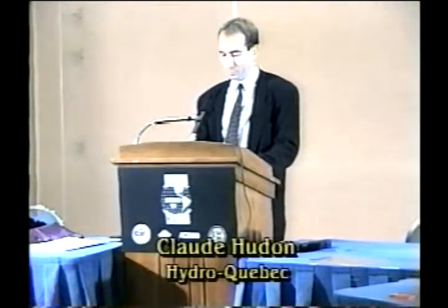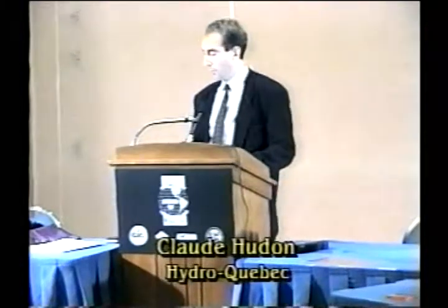Presentation today on turn insulation aging of motors exposed to fast pulses of inverter drive will be divided as follows. First, after a brief introduction, I will describe the differences between AC voltage and pulse width modulated, or PWM, voltages. We'll see how the insulation will be stressed in both of those cases, and I will describe how the characteristic change of the insulation can be characterized.